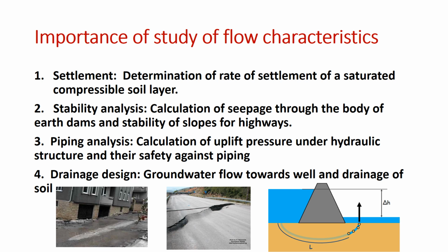Now, importance. Though we have discussed permeability briefly, one is settlement: determination of the rate of settlement of a saturated composite soil layer, because whenever we design the foundation of a building or any other structure, settlement is very important. Then stability analysis: we know that all slopes should be stable, whether they are on highways or railways or even earth dams or even on hills when we have road cuttings. So that analysis is to be done.